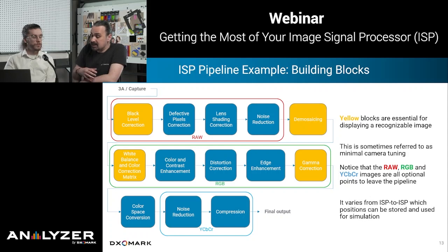There are, anyway, a certain number of commonalities that we can identify, specifically the fact that there are several color spaces that are going to be used in your pipeline. When you take the image from the sensor, it's not even an image yet, it's a raw file. A raw file is a matrix of values in which every value, every photosite, is represented with just one number.